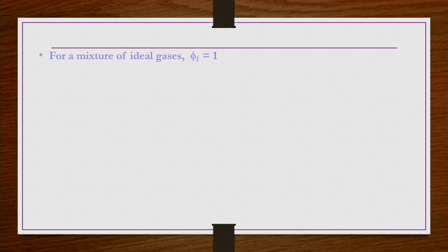Okay. So, what is the point? What is the importance of this activity coefficient and fugacity coefficient? First, they are a kind of auxiliary functions used to relate chemical potential to the temperature, pressure and then composition of the system, plus they are also a kind of indication about the degree of non-ideality that is present in vapor and liquid phases respectively. If they are equal to 1, that means vapor and liquid phases are ideal phases.